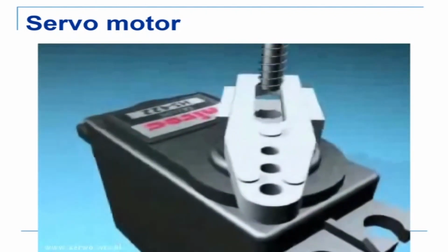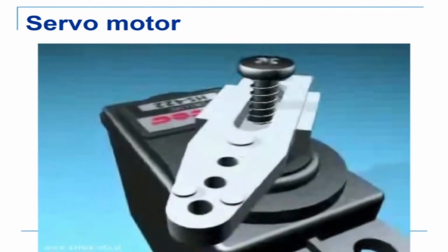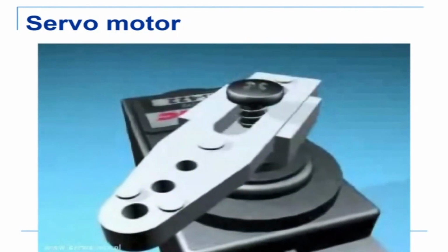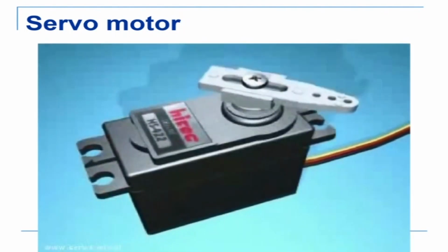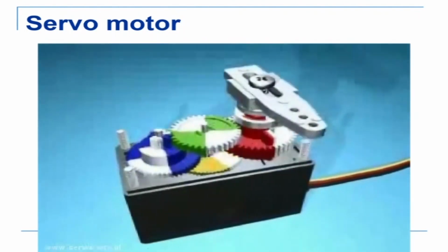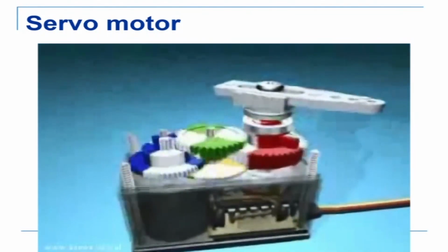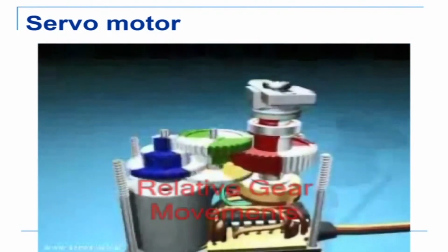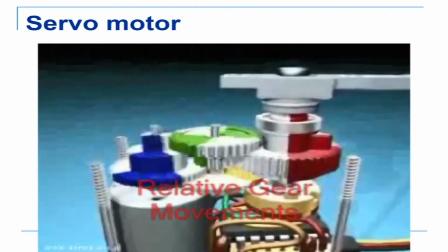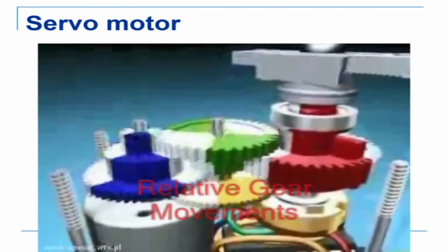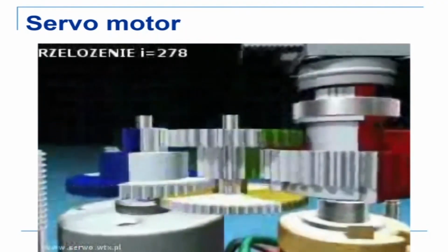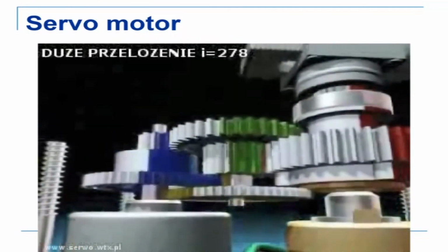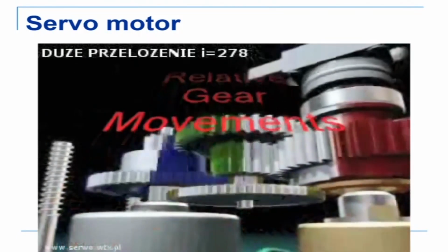So this motor has a sensor, a controller, an actuator, and it is pre-calibrated. So it's very easy to control the position of a link simply by using this servo motor. These are very cheap. They cost about 500 rupees to about 2,000-3,000 rupees. They are pretty good because you can very easily control a DC motor by using one of these. Otherwise, you'd have to build the whole control structure yourself, which is not very easy.